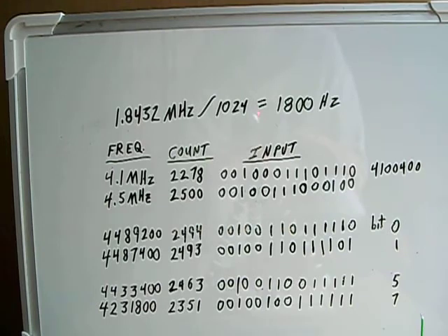The 4 lower frequencies are the ones I'm going to use as demonstration. I needed to find a reasonable count that I could just select a single bit to change the frequency. The inputs have internal pull-up resistors, so to select a frequency I tie one of the pins to ground, and that changes the count.